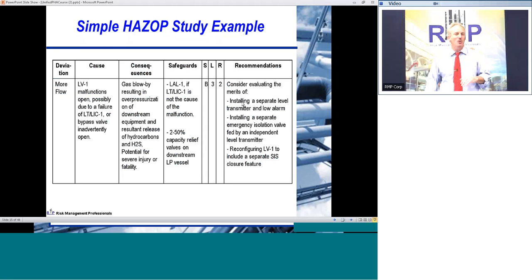That's typically how we approach all our studies, is we do use HAZOP or some other tool for a broad baseline of what can go wrong, and then for the areas that you're not sure or you need more information, then you drill down and get additional information, apply a LOPA or something else to get the information you need for proper decision making and design modification if necessary.